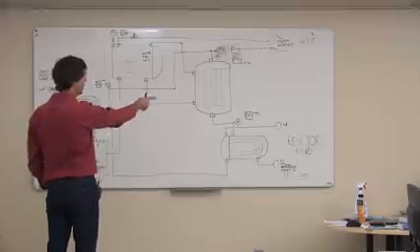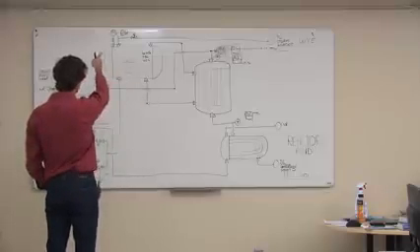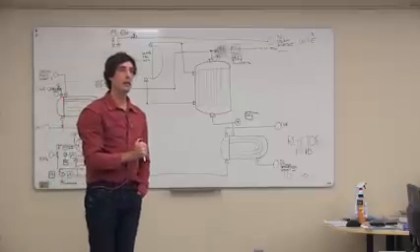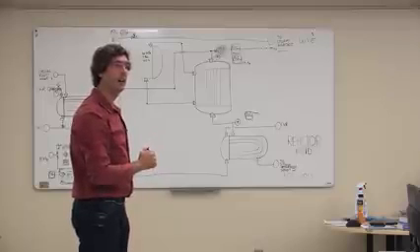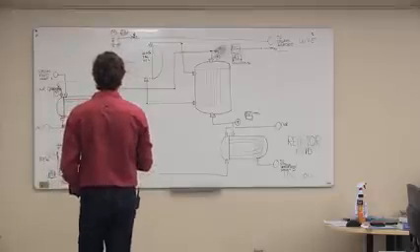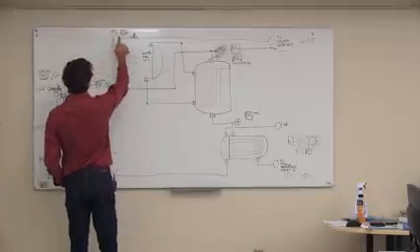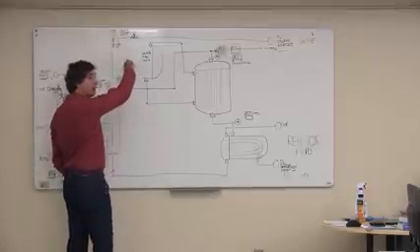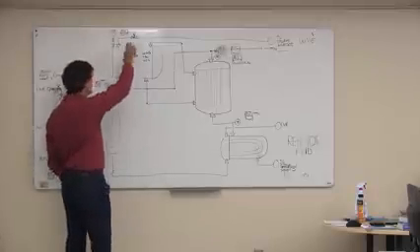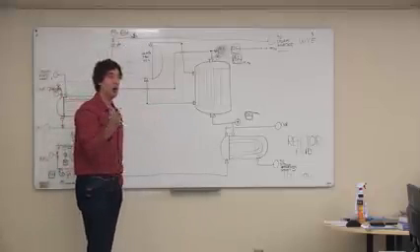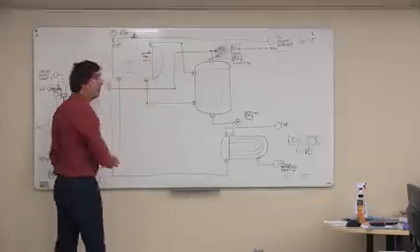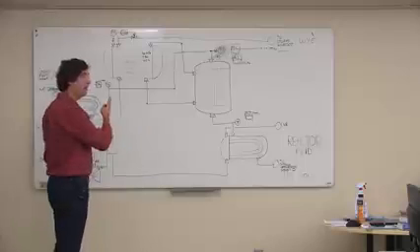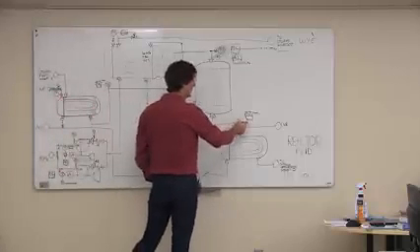Okay, that's good, but how do we relate that temperature? How do we get that temperature to control that pressure controller? So what we need to do, right, is we need to be able to adjust that pressure to anything we want. So the set point of that pressure, maybe it's 10 bar, maybe it's 12 bar, maybe it's 10 1/4 bar, whatever the pressure is. We want that pressure to be adjustable, and we want that pressure to be adjustable based on what the temperature is down here.